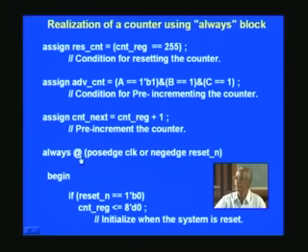This is the sequential circuit as such, and prior to this one we need to do the incrementing of the counter. So, so long as this advance count is asserted, and at the positive edge of the clock, in order to do this one, we can do the incrementing right within this always block, but a better thing would be to pre-compute it, so that you don't waste time when the clock strikes and you start computing. You pre-compute and be ready with it. When the clock strikes, you merely transfer the result. So that would be a good design approach, and that will once again speed up the operation of the system.